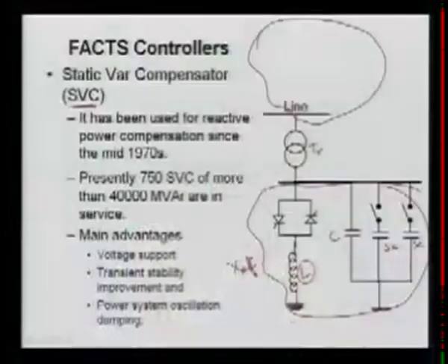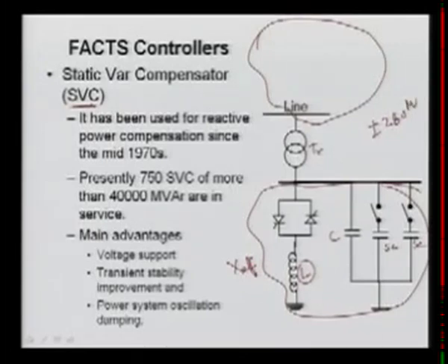Here at the Power Grid station near Bhauti in Kanpur, we are having the SVC, whose rating is plus minus 280 MVAR. Basically we are having two devices, each plus minus 140, and that has been doing the purpose from the early 90s, so it is from 88 and 89 onwards.